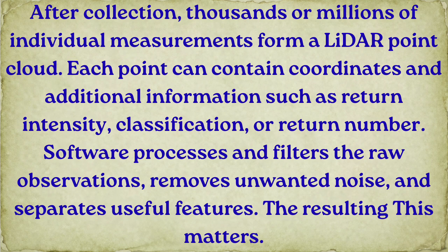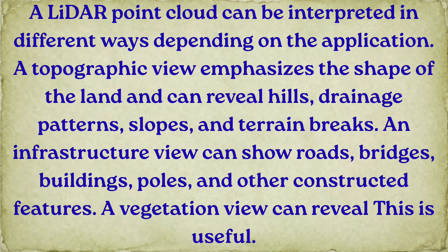Each point can contain coordinates and additional information such as return intensity, classification, or return number. Software processes and filters the raw observations, removes unwanted noise, and separates useful features. A LiDAR point cloud can be interpreted in different ways depending on the application.